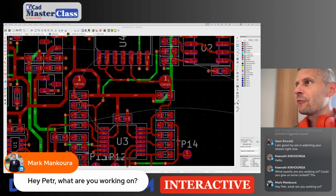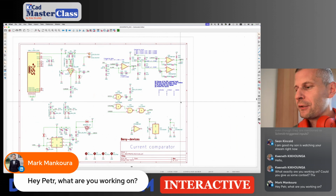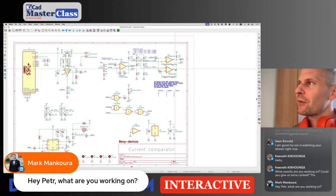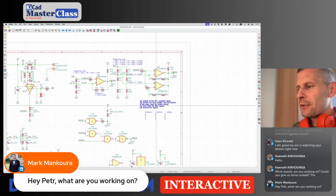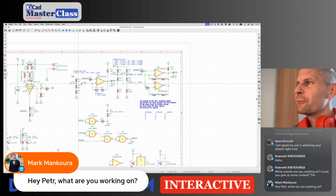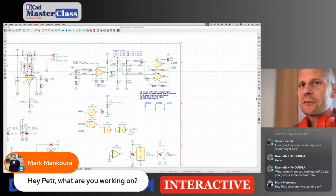I am slightly modifying the current monitor, the current comparator board I designed two months ago. I verified the prototype last week, and half of the comparator didn't work because I swapped the inputs of the window comparator. So now I'm working on these changes of the window comparator, plus I added some test points, and reconsidered the entire design. It seems that like 50% of the design worked, maybe 75. One of the comparators didn't work, the window comparator.